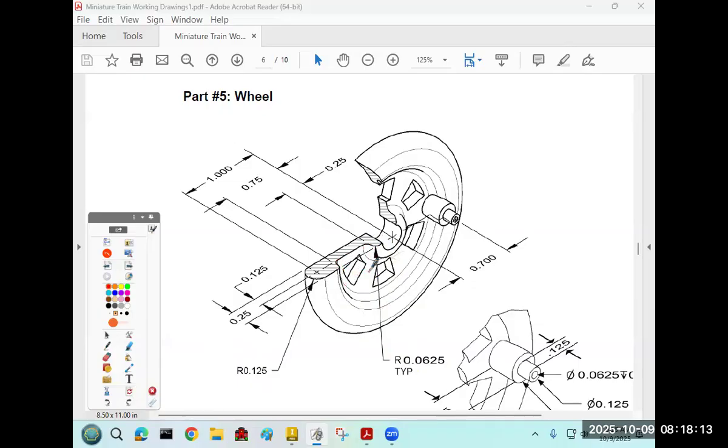But of course, we're going to do fillet after it's apart. We're not going to do the sketch fillet. Okay? And since we are used to drawing our sketches like we did with just that, where we draw everything to the right of center and then revolve it, we are actually going to sort of twist this, where the shape we're going to draw is going to be something like this. Okay, which is this shape right here. Okay, and this will be our center axis, and we'll revolve it around that way. So we need to sort of infer those dimensions.